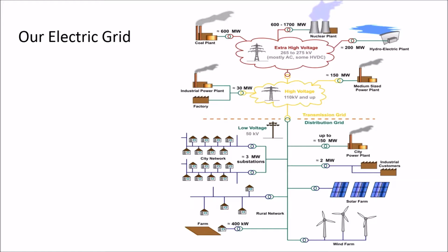to interconnect a solar array to the grid, you have to program the inverter not to export any power onto the grid. And you might think, well, that's funny because I'm interconnecting to the grid so I can sell the electricity back. The utility says, no, you're not allowed to do that anymore. The consumer could get upset and say, well, PURPA says you have to, and the utility says, look, we can't even buy the electricity if we want to, because what you're interconnecting to the grid is making it unstable. So we can't allow you to export power, not because of us wanting to buy electricity or not, but because the infrastructure can't handle it.